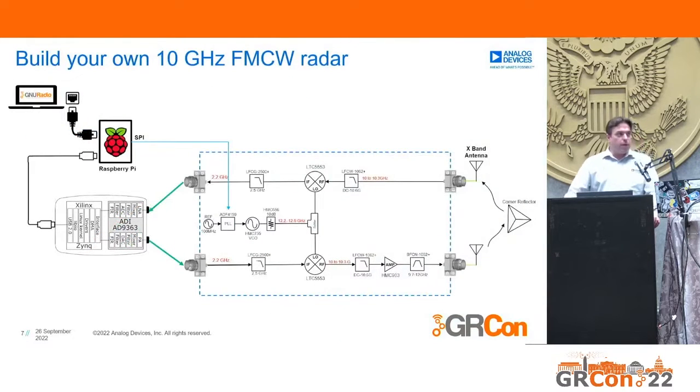Thanks to John Graft, who helped me prototype this, and was also so kind to actually build that up and take a video. We're going to see that in a minute, but here is the top level overview. We have a digitizer. In this case, it's an ADALM-PLUTO. It can be any USRP or any other SDR, because we have pretty low bandwidth on that side. Then we have the RF front end that's composed of a number of blocks.